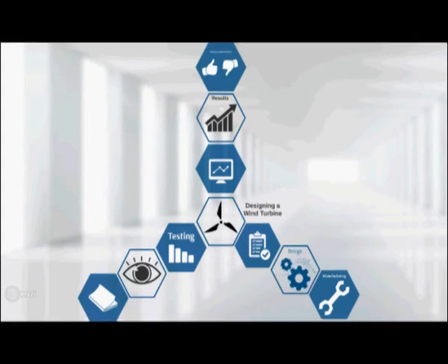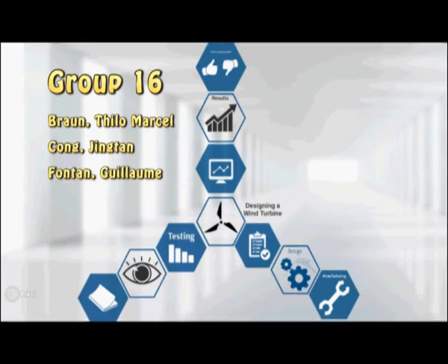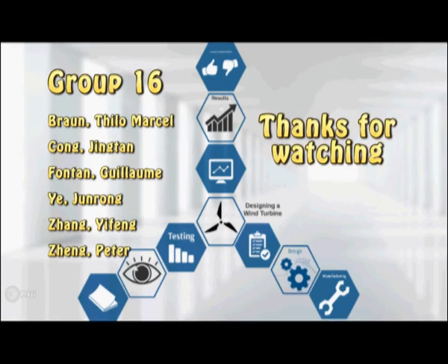We were able to extend the operating envelope by making some modifications to the geometry, which yielded a comparatively high merit function. To bring the turbine to practical applications, a general focus should be put on extending the stable operational envelope, both to lower and higher wind speeds, depending on the application. Based on the average UK wind speed of 4.5 meters per second at 10 meters height, the design may be easily adapted for small-scale private deployment.